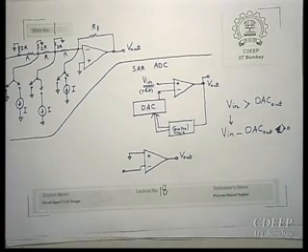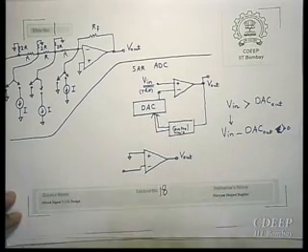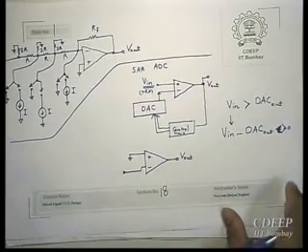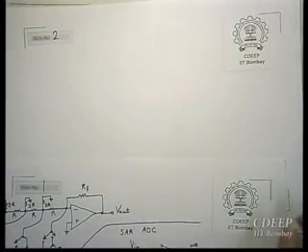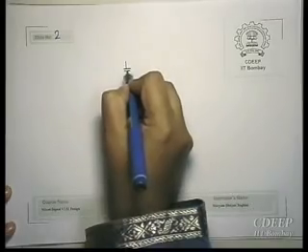And now this subtraction is actually done on the capacitor itself. So we sample, subtract, and compare it with 0. This is the whole idea behind this cost-effective, or component-effective, SAR ADC. So now we come back to that binary weighted capacitor.